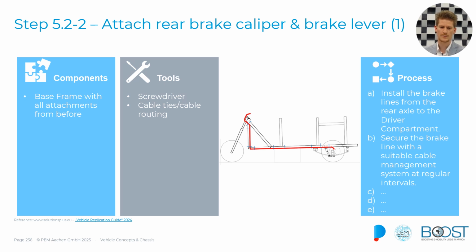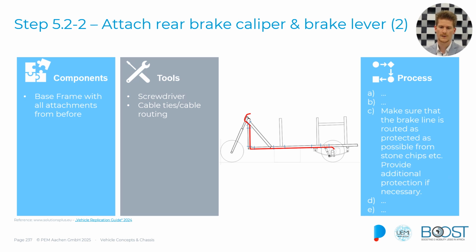The next step would be to make sure that the brake line is routed as protected as possible, so that there are no stones that could hit it or anything that comes up from the road that might penetrate the brake lines.